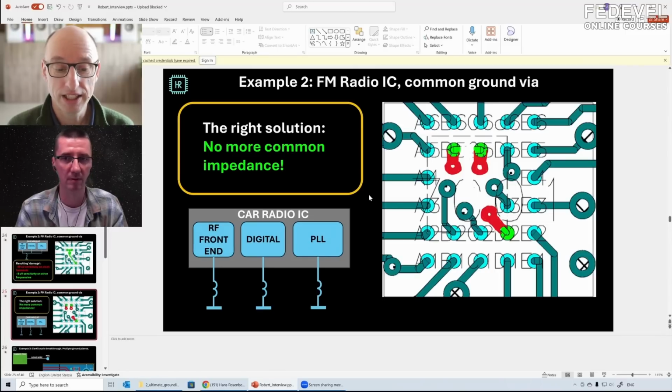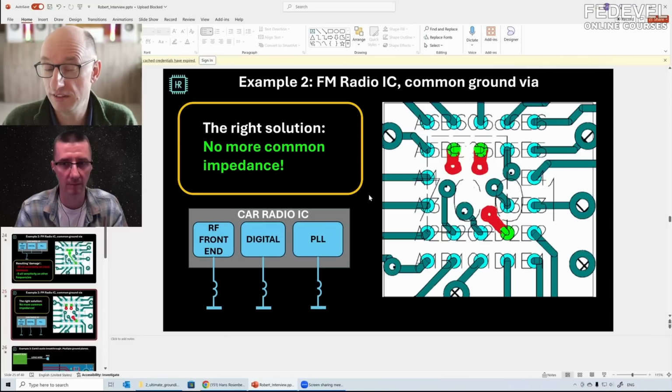Yeah, sometimes, if you're making something like an FPGA board, you're so limited in space, and then you have to make a conscious decision like, okay, I have 3 digital ground pins. Can I put them together in 1 via? Well, in that case, there's not so much damage because they're all the same. You're not connecting a very high dynamic range ground to a digital ground. That's a disaster. So that's why it's always good to understand the theory behind this, because then you can make a conscious, educated decision on what is best.